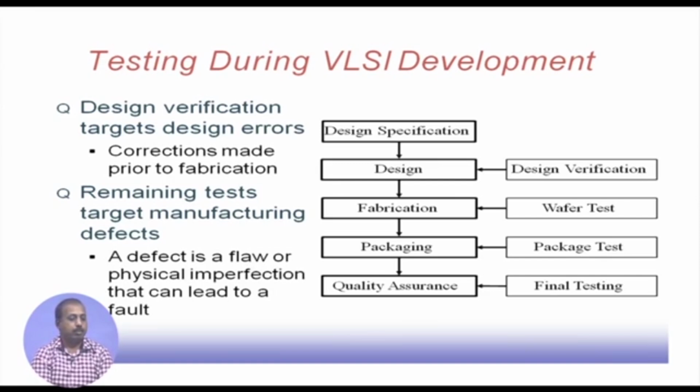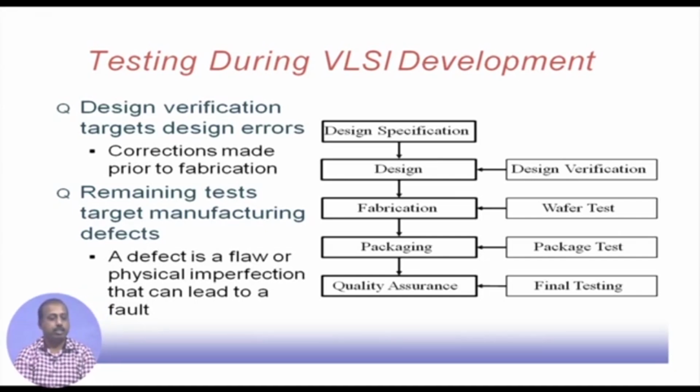Now, once we have got the confidence that my transistors are all fabricated properly, it comes to the packaging stage. In the packaging stage, the packaging will be done. Now we will have this bonding of the chip, and at that point also we need to check whether this packaging has been done correctly, the pins that are created, whether the pins are connected properly to the system or not. So, those types of checks are to be done. That test is also necessary at the packaging level.